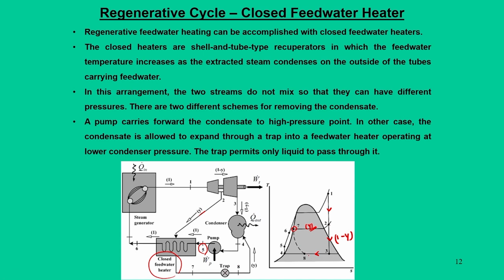Thereby the condensate or liquid comes out at state 8. So, the entire fluid mixes at 8 and then again goes to state 4, and state 4 is nothing but the condensing unit, and from then the entire process is repeated and we get state 5 at the exit of the closed feed water system.